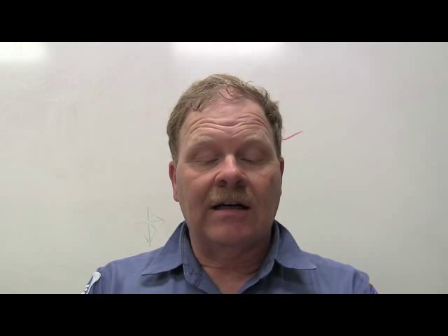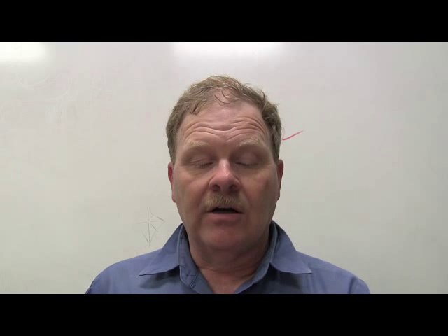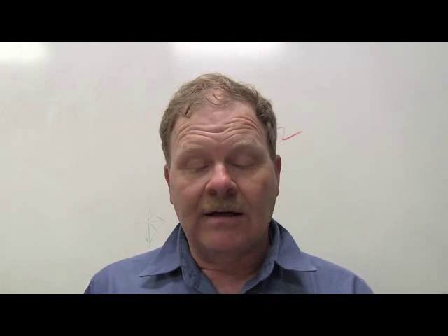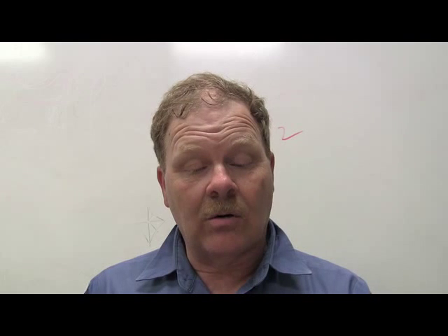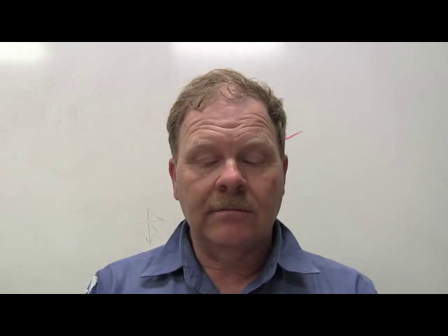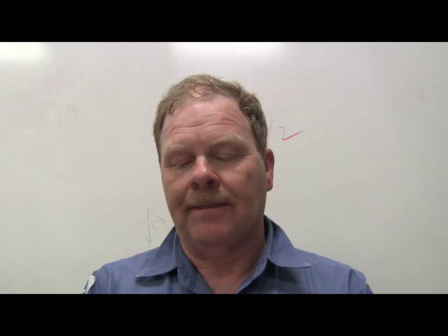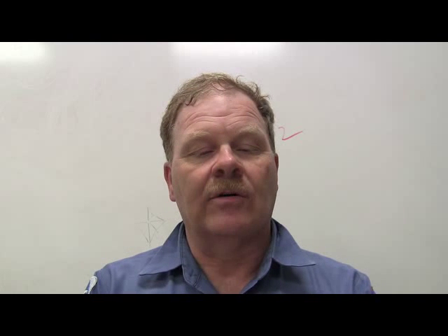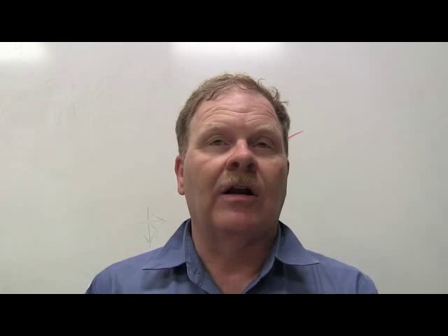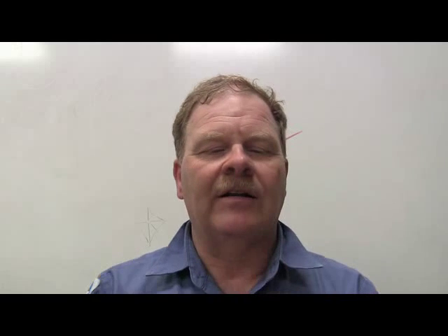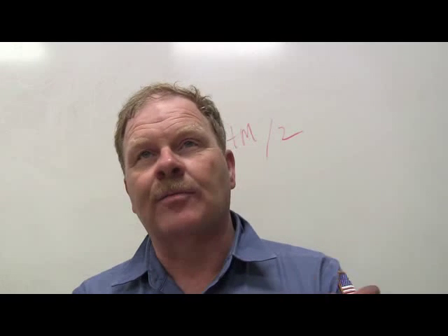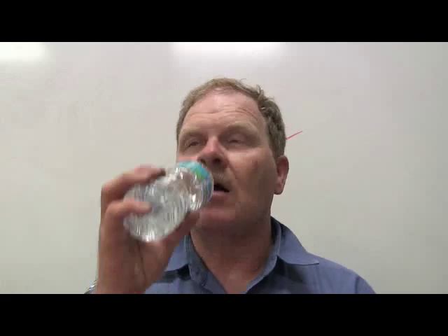Two technicians are discussing thermal expansion valves. Technician A says the TXV senses evaporator temperature to control the valve opening. That's what I was saying earlier. Technician B says the TXV senses the evaporator pressure to control the valve opening. Is it temperature or is it pressure? It's actually both, because pressure and temperature run hand in hand. A lot of the times these evaporators will have a little sensing bulb on a long alcohol tube that'll have some of that rubbery tape, that pressed tape, taping it to the evaporator tube. And in that case, it infers pressure by checking the temperature.